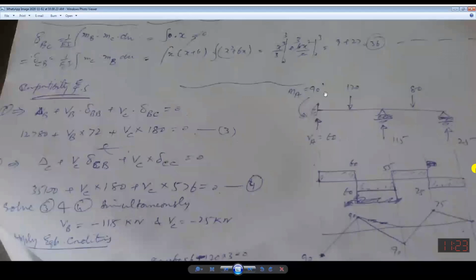This moment can be found, this force can be found. Sigma fx is simply 0. It's well known. Don't need to go into detail this one. And also, it should also be noted that in the horizontal direction, the beam is so stiff, it will not be moving rightward. So we will not be considering its deflection along the x direction.